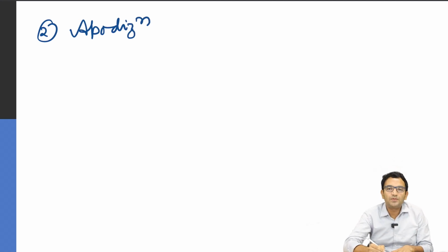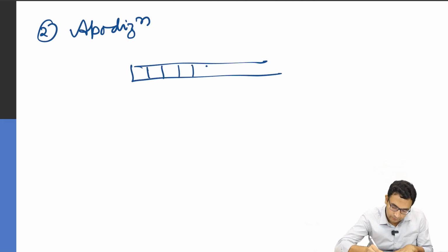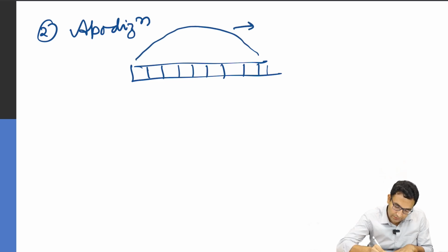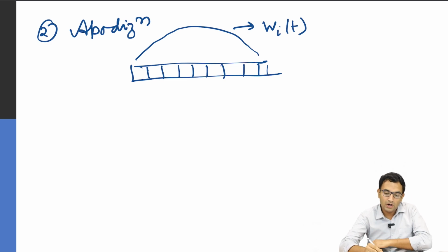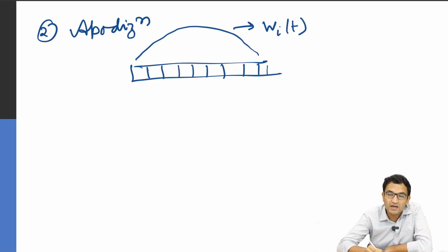So the signal from each element is given a weight, right? If you recall, let's say these are the elements in question, we will be providing a weight. This is my weighting function. Now remember, when I am weighting in apodization, it is essentially a gain of the transducer elements in terms of amplitude. This is not the delay profile that I am showing you here. There might be a delay profile also associated, but this function represents the relative amplitudes.